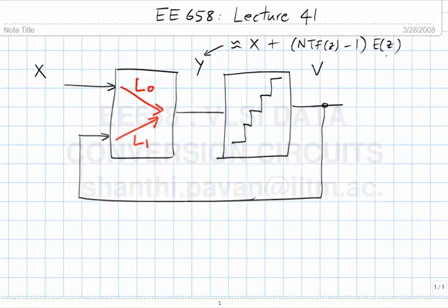We also saw yesterday that the variance of the noise at the input to the quantizer, because this basic quantization noise which we have treated as additive has propagated through the loop, is certainly not delta square by 12, but a large multiple of delta square by 12. And this large multiple gets larger and larger the moment the order gets higher.